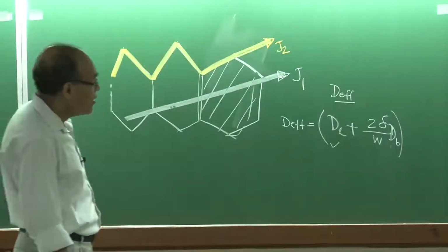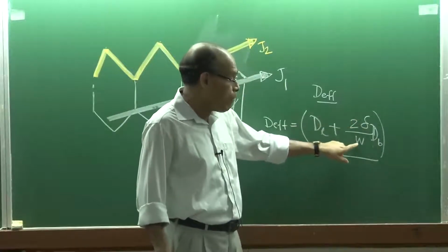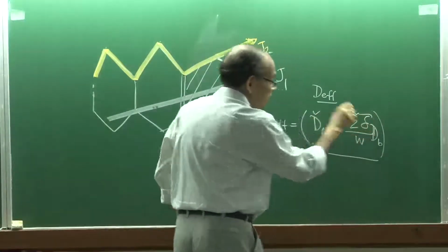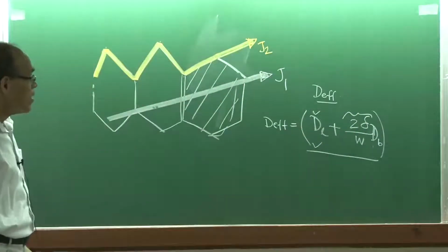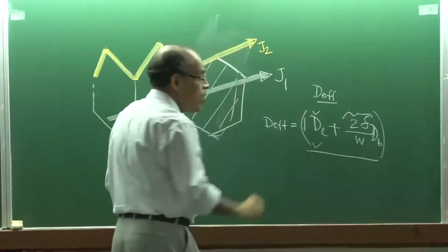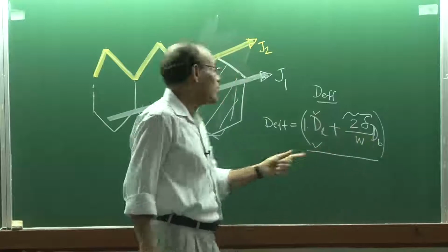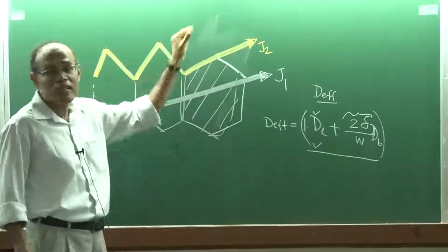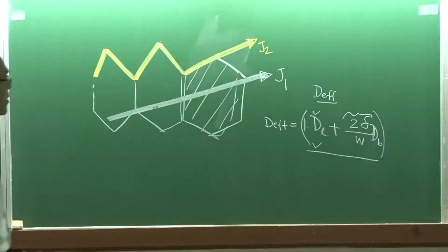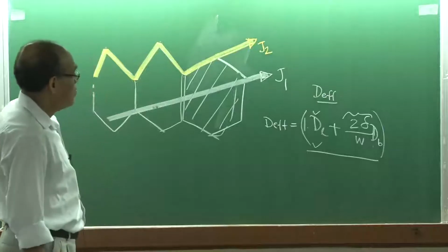And this is an application area, and there we see that it is not just the lattice diffusion coefficient which can predominate, because the boundary diffusion coefficient is multiplied by a parameter where W is very, very large in comparison to delta, which implies that this factor, vis-a-vis the entire factor, will determine which of the 2 parameters dominates. So even though this coefficient, delta by W, is much smaller, and this coefficient here is 1, even though the coefficient is larger here, that does not necessarily mean that the lattice diffusion will predominate, because the boundary diffusion, because of the structural inhomogeneities present in the grain boundary, could actually turn the ball to the other side.